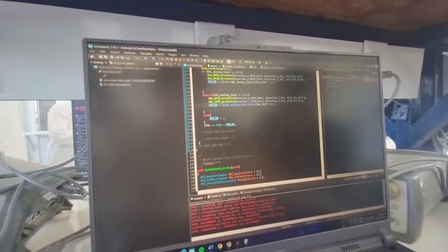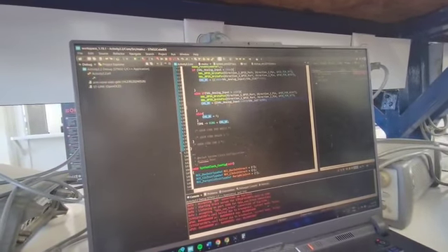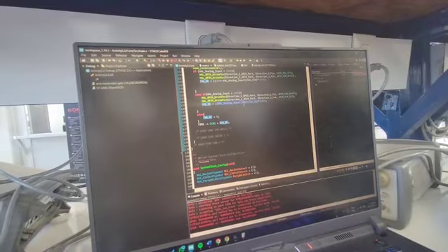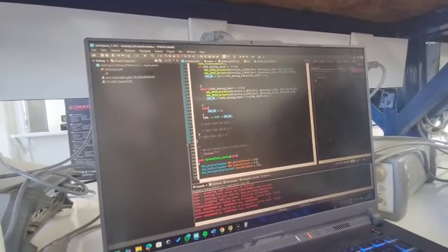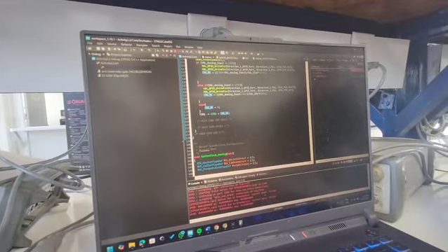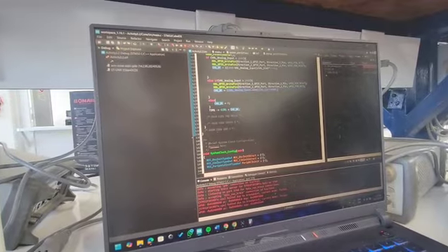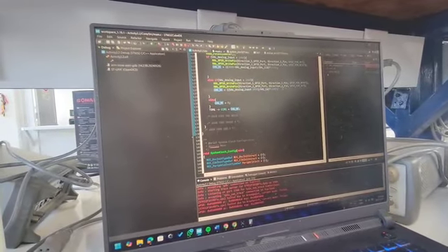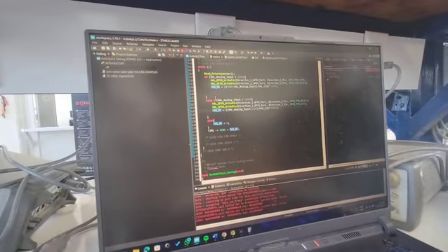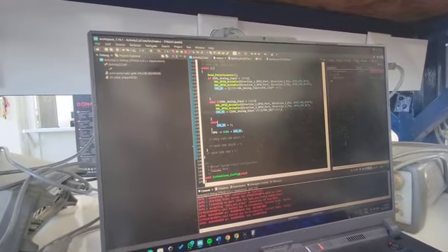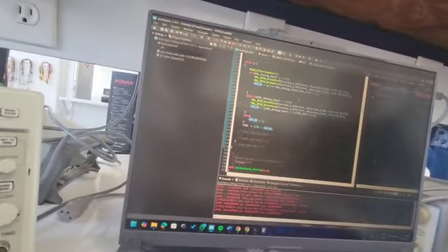We subtract 2400 and we do the same trick to get the duty cycle in this part, and then multiply by the 36,000 ARR value, so we get the correct CCR value in the program, and this will give us the trapezoidal figure depending on the analog input that the project requires.